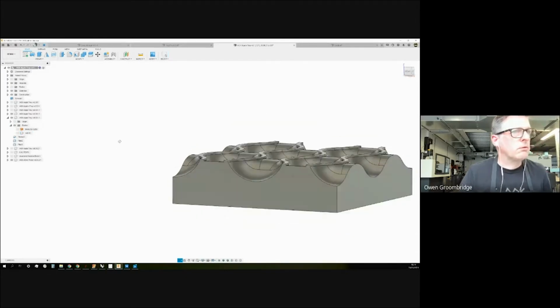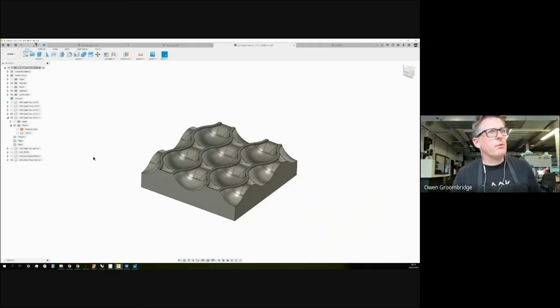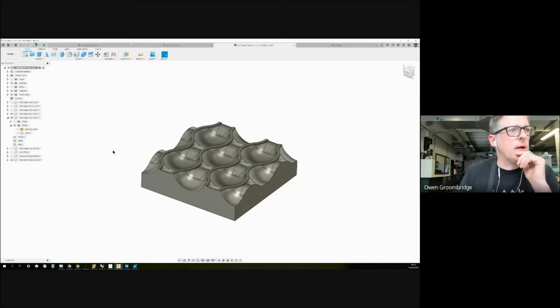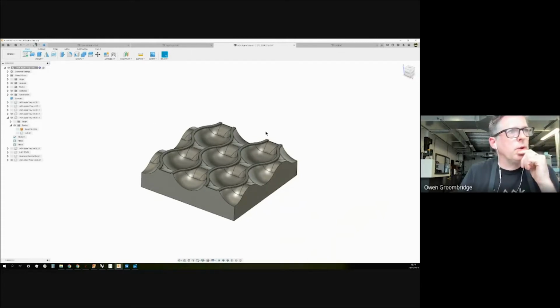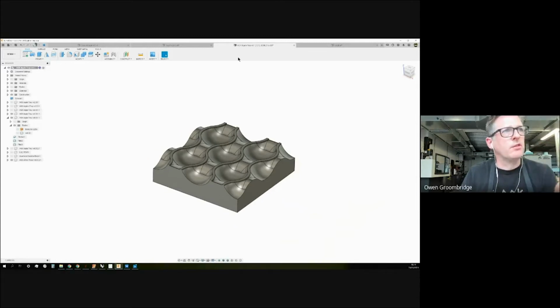Okay. So derive. What is derive? In order to derive something, if you were ever to do this, you have to have it as a saved project. I know this isn't saved because right at the very top it says the file name, but at the end it's got version 35 with an asterisk. That little star symbol, that asterisk, means it's not saved. You can't use derive. Okay, I'll give it a go.